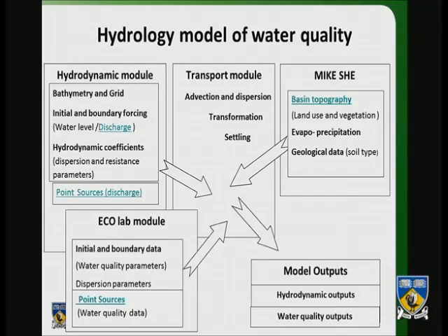And other thing is, we did a survey and tested their water quality, but we didn't do the survey for all 300 companies. For the other companies, I have the information about their wastewater discharge, as well as whether they have a wastewater control unit or not. So based on that, I estimated. If it is a garment industry and they don't have any treatment plant, we know the standard BOD level and the standard COD level. So using that, we estimated pollution loads.